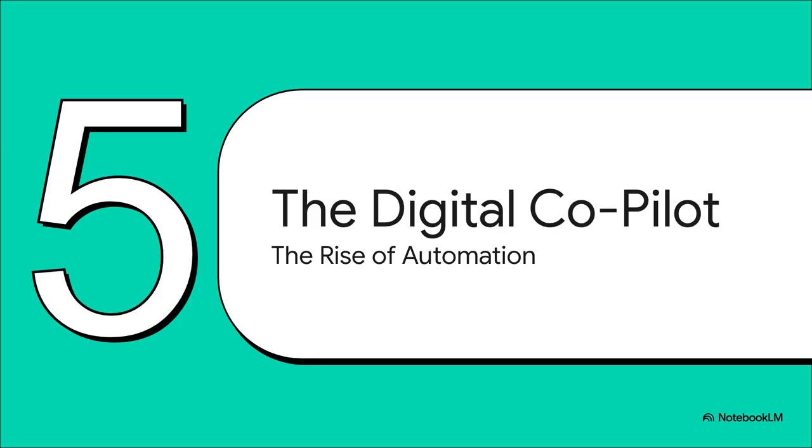Okay, so we've gone from muscle power to hydraulic help to computers. The final step in this evolution, well, it's handing over a big chunk of the workload entirely to a machine. So when we talk about a modern autopilot, how much can it actually do? How many of those axes of flight can it handle? The answer is all three. A standard three-axis autopilot can control the roll with the ailerons, the pitch with the elevator, and even the yaw with the rudder. It uses gyroscopes and navigation data to fly the plane completely on its own.